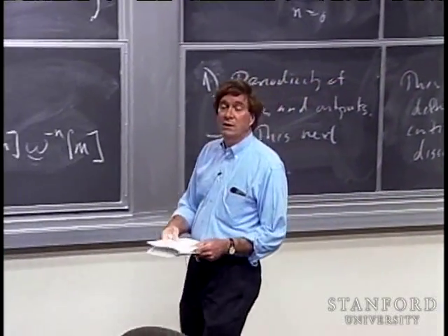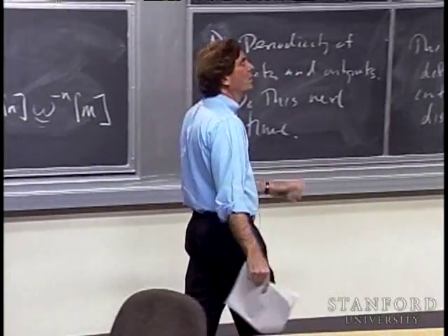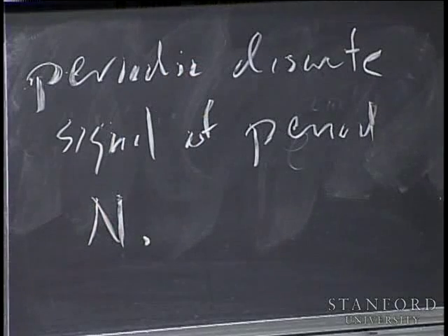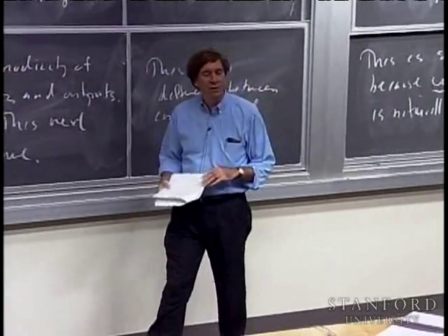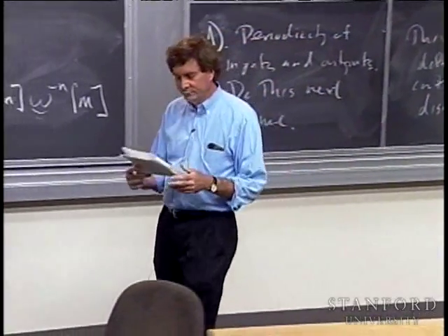This actually turns out to have significant consequences. Whether or not you use it in a particular problem in a particular setting, it's lurking in the background: the input signals are periodic and the output signals are periodic. And in some cases, it has consequences for computation. All right, in some computations, if it's not taken into account, you can get results that are not in accord with what you might expect. And it usually has to do with not taking proper account of the periodicity. Sometimes you have to shape the signal a little bit differently to take that into account. So more on this next time, but I did want to mention it.